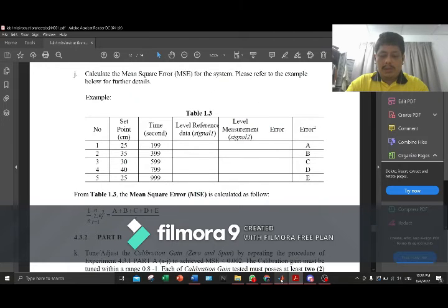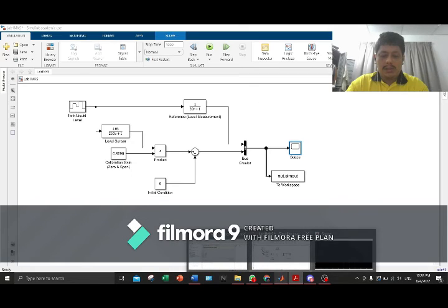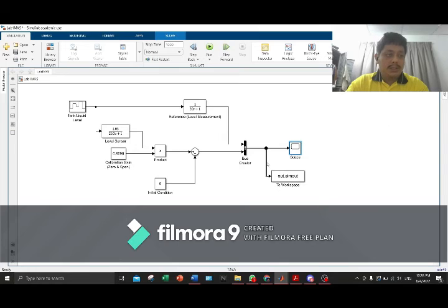First I'm going to show you the Simulink circuit. This is the gain. I have changed it to 0.9698. Why are we using the 0.9698 value? Because we get the final result of the MSE as required, which is less than 0.002.